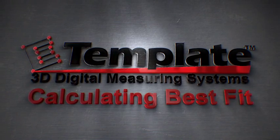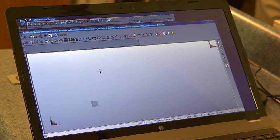So now we're going to go ahead and measure the walls, and we've used the automatic leveling capabilities of the laser to define the floor as our datum plane. So when we go to measure the walls, we'll be able to see exactly how plumb the walls are for our CabinetVision design. Since we've established the floor as our datum, we're going to go ahead and measure the walls.